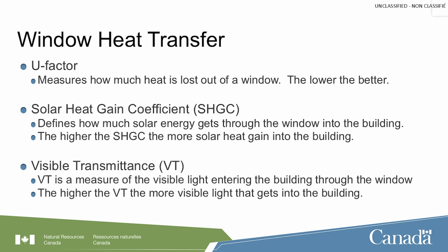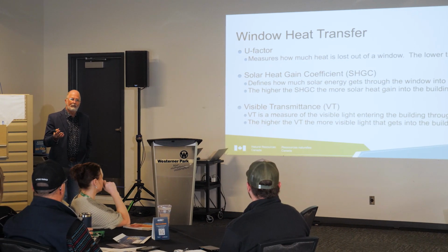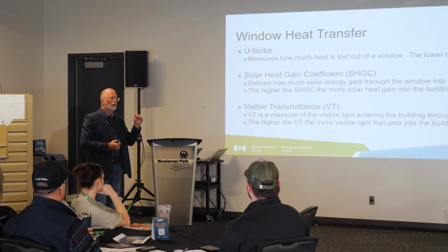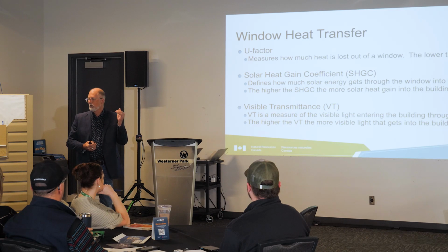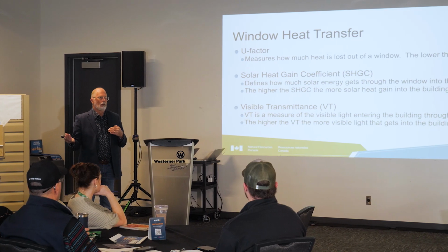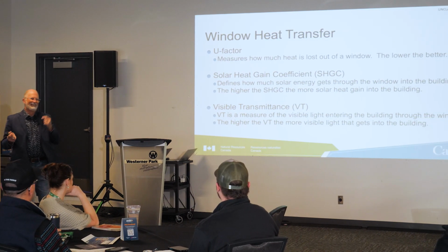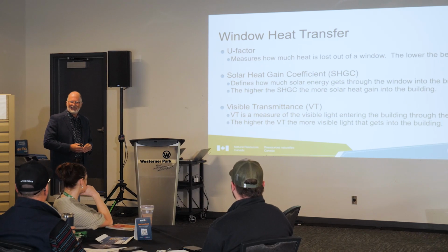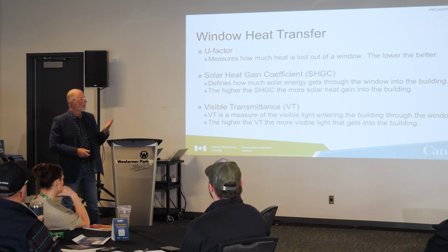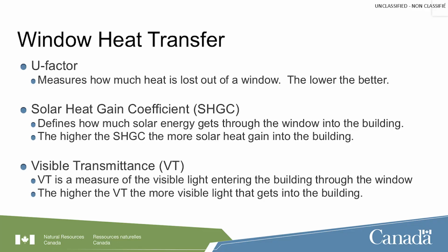We have a U factor, and we always want to look at a metric U factor. Understand the U factors. If we're into the 1.0, 1.2, 1.6, that's a metric U value. If you get something from your supplier that says 0.4, 0.28, that's an imperial U factor. How do you convert imperial to metric? Calculator, Google. 5.678 is your calculation, right?